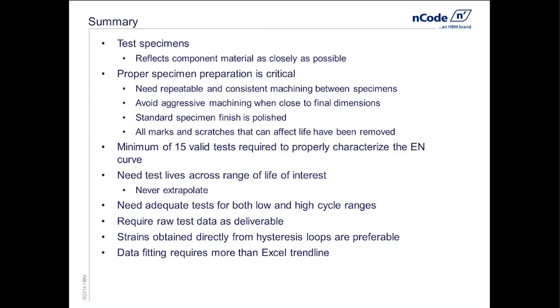And then finally, in terms of data fitting, the actual fitting of this data is more complex than just doing an Excel trend line. We're actually controlling the strains in the test, and the lives are the outcome. But basically the lives are the x-axis and the strains are the y-axis of our curve.